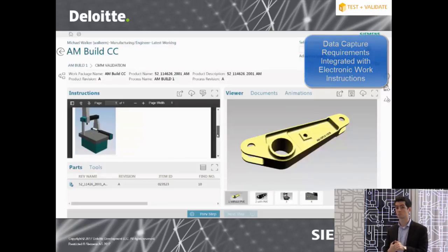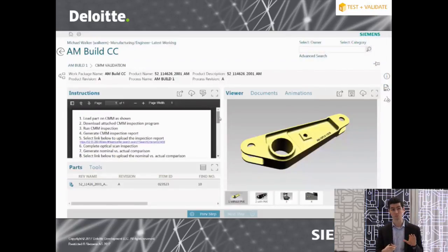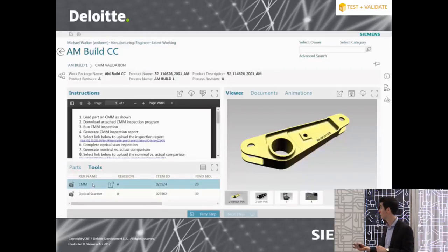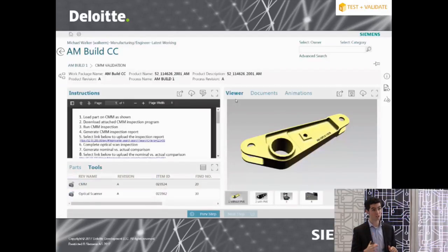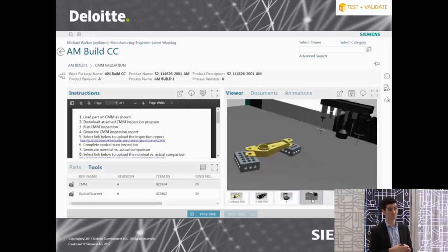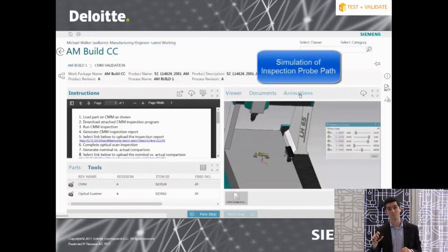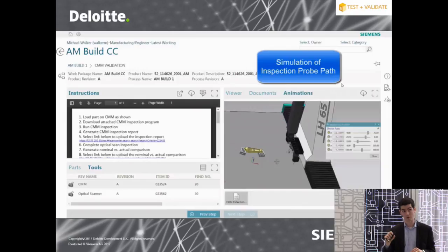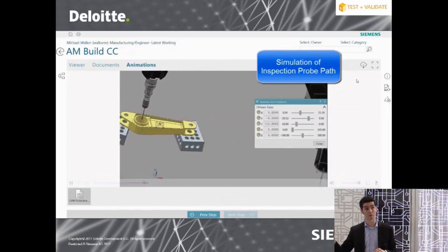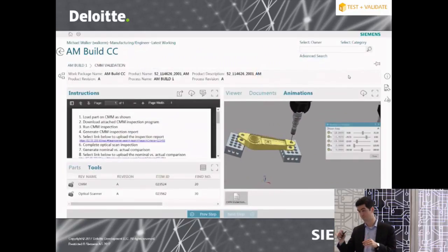So for the coordinate measurement machine, we're talking about a probe that's going to check high priority areas of the part for both its measurement as well as its surface finish. And it's actually automated based upon the PMI data linked to our 3D model. So again, that's under configuration control and actually can be automated in terms of the path from NXCMM. But beyond automating that probe path, you can use the information off of your in situ monitoring data to change the priority areas of your part that you might want to inspect, to prioritize more areas in that bottom right hand corner, like where we saw where the red areas were on our 3D model.